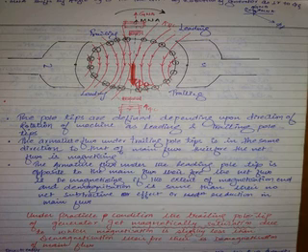Listen, mathematically, phi A and phi F are like this. What is the net flux? This is the net flux when there is no armature flux. When there is armature flux, this flux becomes like this. These two are mingling with each other in the machine, reacting with each other, and due to armature reaction, the net main flux became like this. Yes or no?